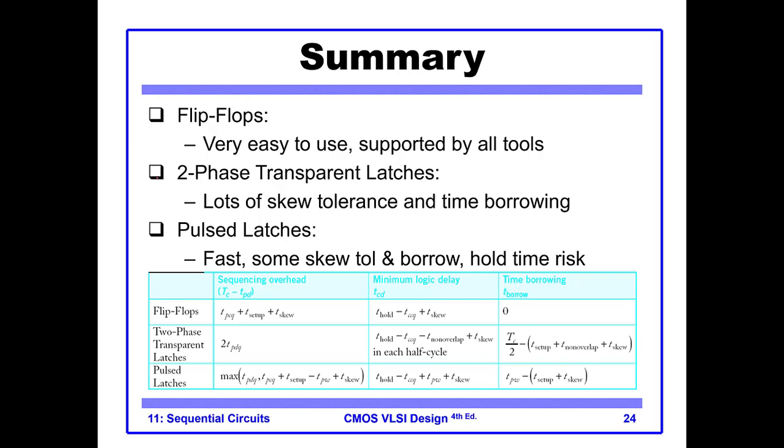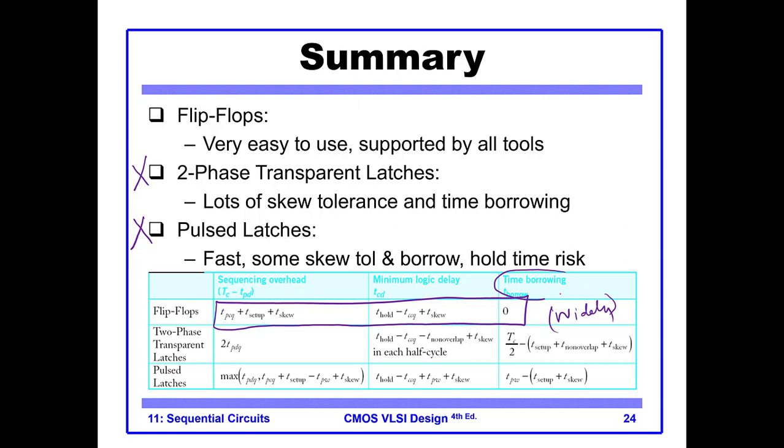So this is the summary of this part of the lecture. We have not discussed this and this in detail, because the most widely used ones are flip-flops, and the formulas for these we have discussed in great detail. We haven't discussed the concept of time borrowing, because time borrowing is only applicable to two-phase and pulse latches, and it is not applicable to flip-flops.